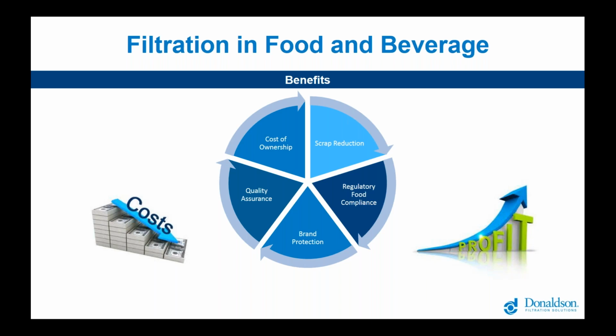And then second to that, since testing of that filter is very important to ensure that it's doing its job effectively over its entire lifetime, you really need to also make sure that there are in place integrity tests that are non-destructive that can be performed, and those tests need to have the results correlated to that original true bacterial retention test. So those two things are extremely important.